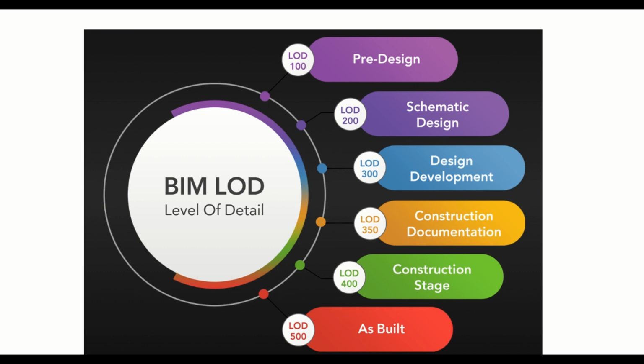For example, we all know that for a WC we need a support, right? So the horizontal or vertical support based on the design, but how many nuts are required to screw that support with the wall, those kinds of stuff are still pending. So that is why we can't directly 100% install all the services on site at LOD 350. But on paper it's fine.